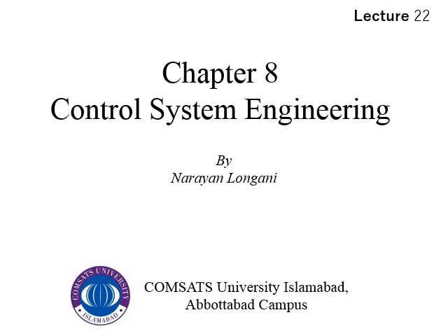We are studying the topic of root locus, which gives us a graphical representation of closed loop system poles when an unknown parameter of the system is varied. In the last class we studied rules related to sketching of root locus. First rule is the number of branches of root locus equals the number of closed loop system poles. Second one, the root locus is symmetrical about the real axis.